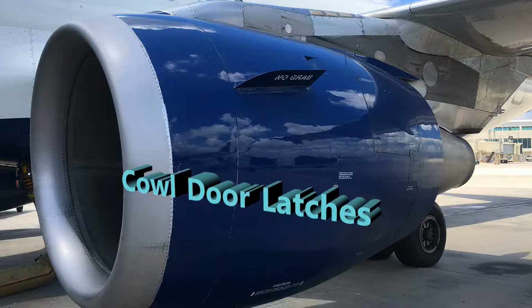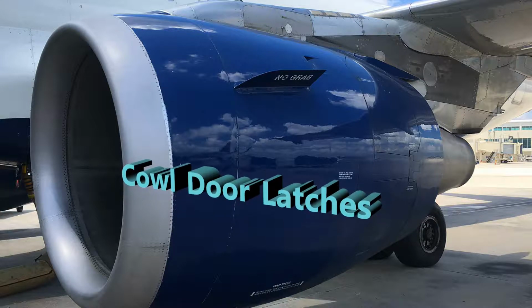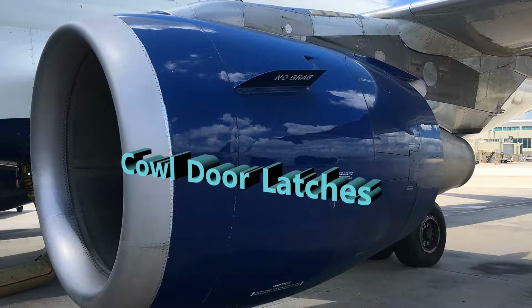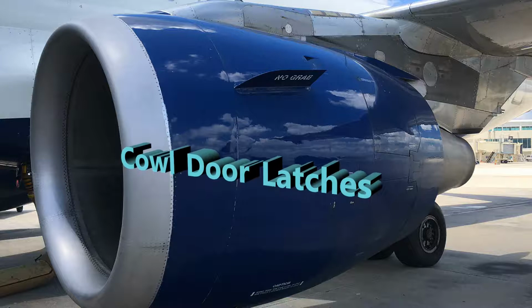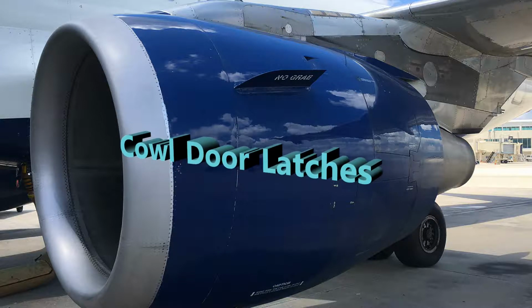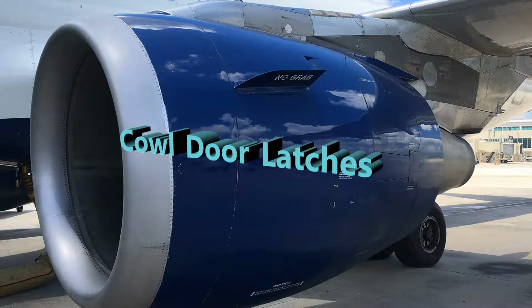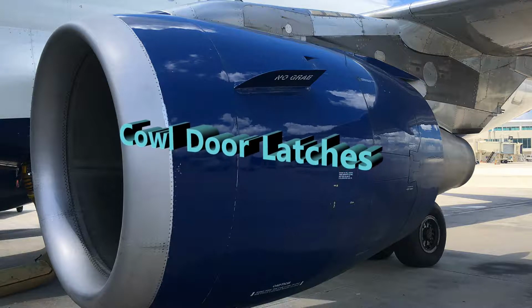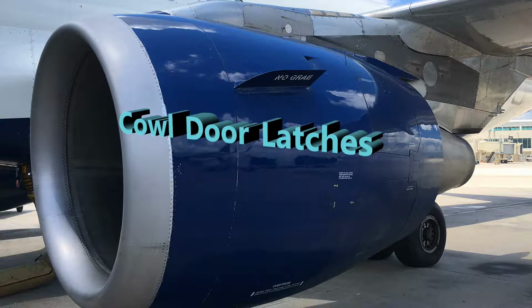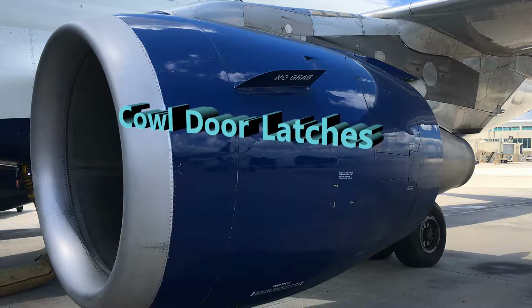With the fan cowls, there are 5 latches, and there's a procedure, and you want to make sure you follow the sequence properly, because if you don't, you're going to cause damage to the fan cowls, any of the cowls. If we're talking about the thrust reverser cowls, same problem, you could potentially cause damage. So do make sure you follow the maintenance manual as what it states for the sequence.